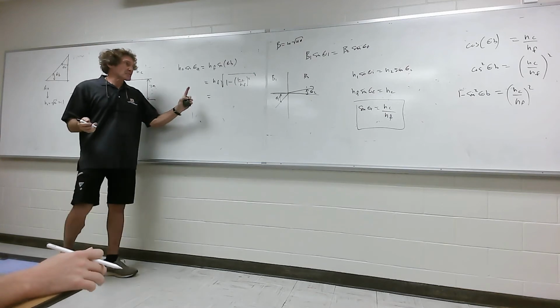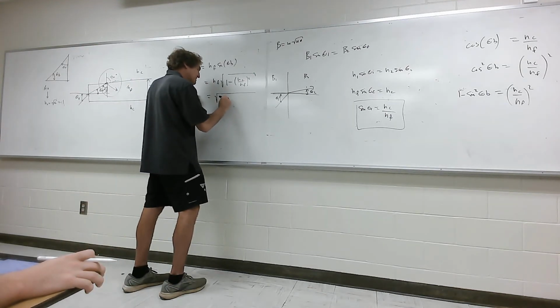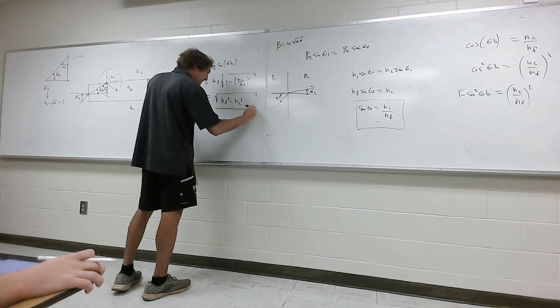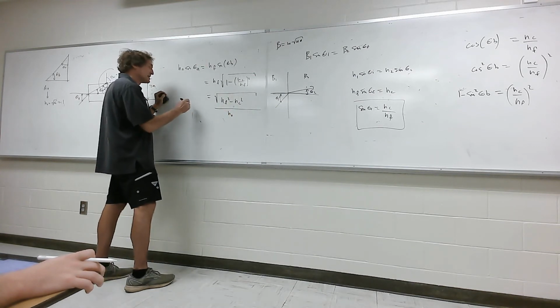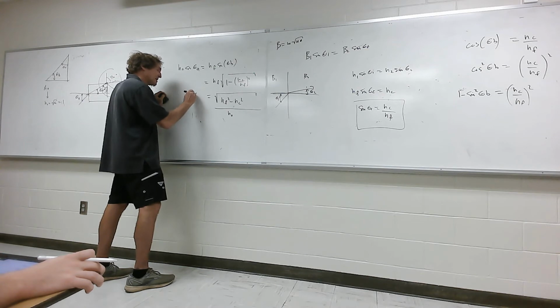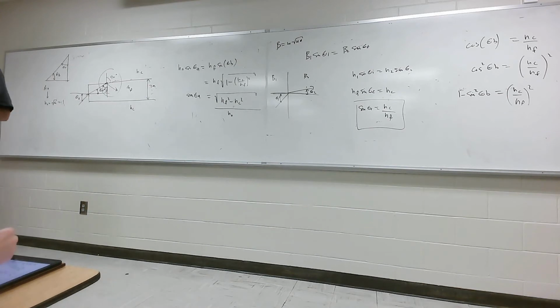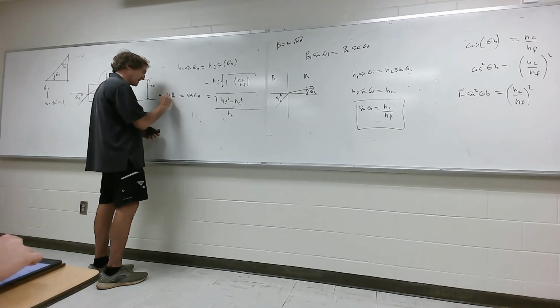And now I'm just going to multiply through with NF, and I get the square root of NF squared minus NC squared. And if you want to, you can divide that by N0, which is usually 1 if it's there, and almost always it is. This is called the sine of theta A. Now we could solve for A by taking the inverse sine of the square root of NF squared minus NC squared over N naught. Y'all follow me? If you want that angle, you can solve it. But the really important thing, this is called the numerical aperture, or NA.